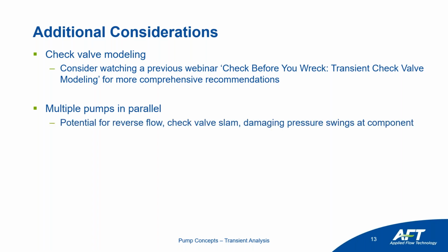Multiple pumps in parallel. So if you imagine having multiple pumps and one of them trips, that's something that you can model in the software as well. That's going to have similar high potential for reverse flow. If you imagine that all the other pumps are still generating all that pressure, now you have high pressure downstream of the pump, it's off and it wants to flow upstream to that lower pressure. So that can cause reverse flow, leading to similar things like check valve slam, and then can also lead to damaging pressure swings at the component itself.